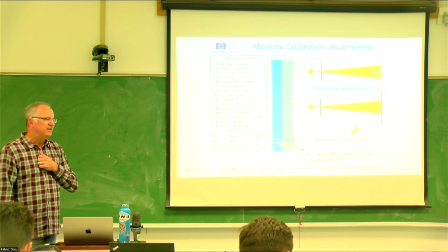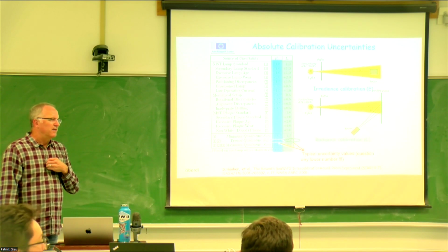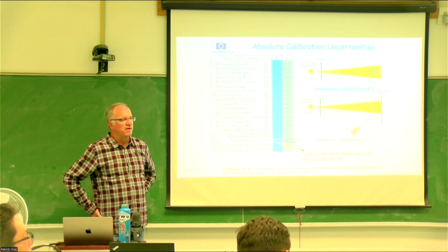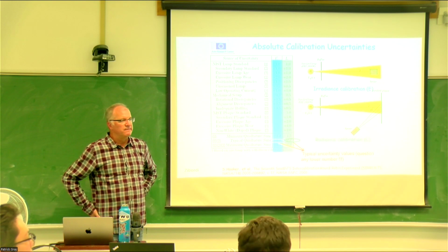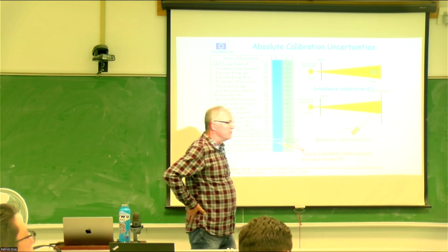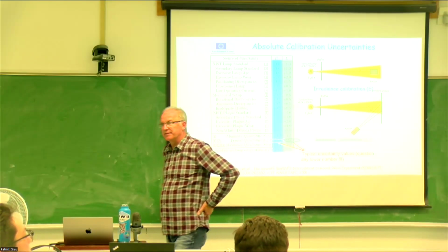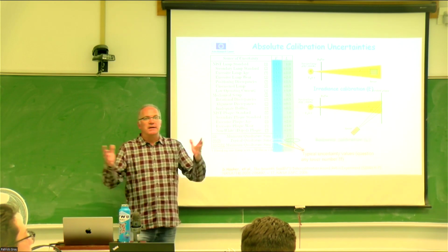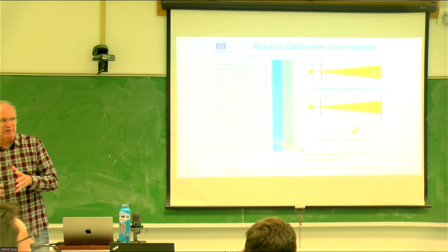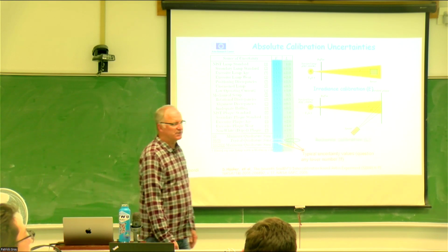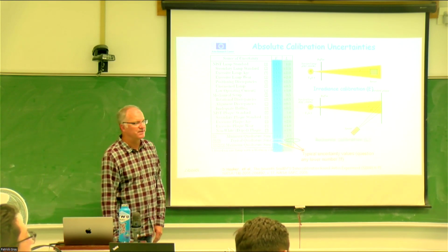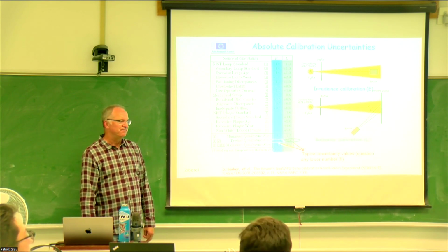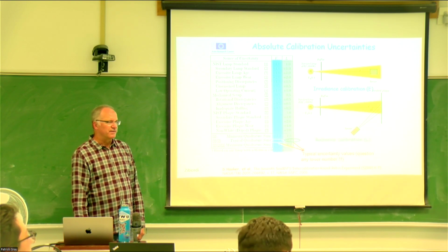Sorry, you had a question? And maybe you mentioned this, but in your calibration room you're setting up, do you filter the air for dust? Yep. Okay. It's humidity controlled because we want to have this constant moisture environment. It's got to be pretty low, not too low. We don't want to get it so cold or so dry in that air that now we're going to get static, which is not great either on surfaces, just as dust collectors. And then you have an air filtration system as well. So yeah, there's a lot that goes into this.